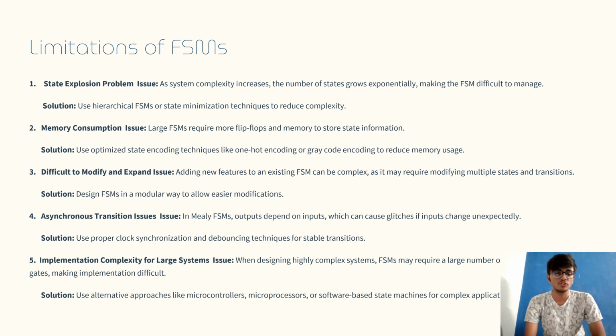And its solution is use proper clock synchronization and debouncing techniques for stable transitions. Fifth one is implementation complexity for large systems issue. When designing highly complex systems, FSM may require a large number of gates, making implementation difficult. And its solution is use alternative approaches like microcontrollers, microprocessors, or software-based state machines for complex applications.